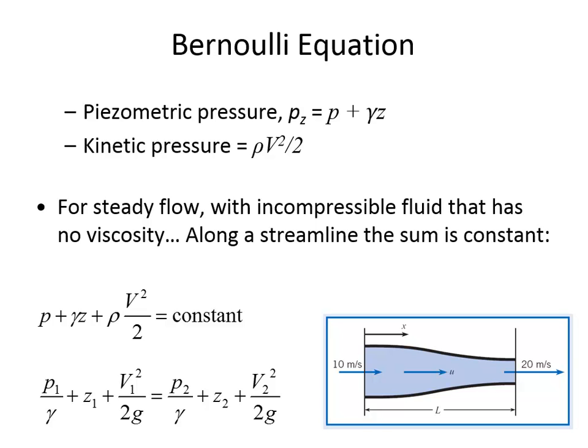What's the benefit of that? Oh, it's just what you've got the data in. There's really no benefit. If you're solving for pressure, then using this form of the equation saves you the trouble of having to move pressure out of the pressure head term. If you're solving for elevation, then maybe that form of the equation is better. They're essentially the same. You've just multiplied each term by the unit weight of water.